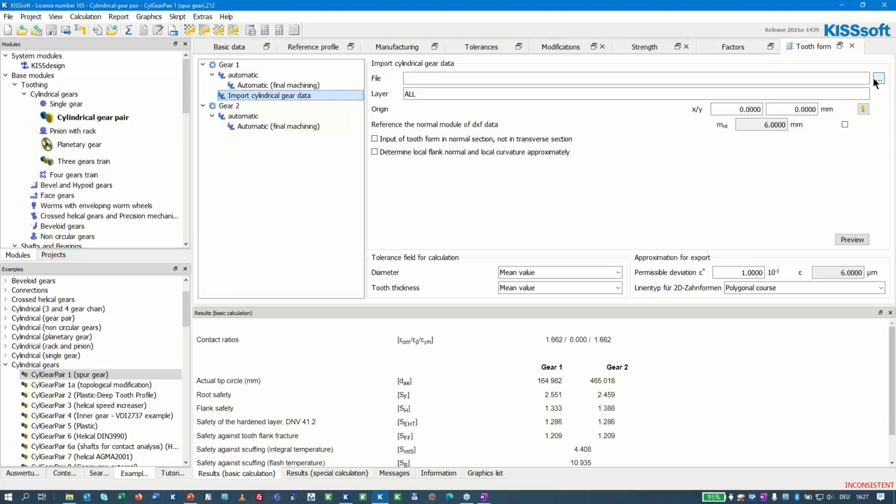Let's say the designed gear is a pure involute of a certain tooth thickness, and you know from experience that, say, at the base of the tooth you have a deviation in thickness by that much, at the middle of the tooth a deviation in thickness by this much, and at the tip of the tooth again another value.